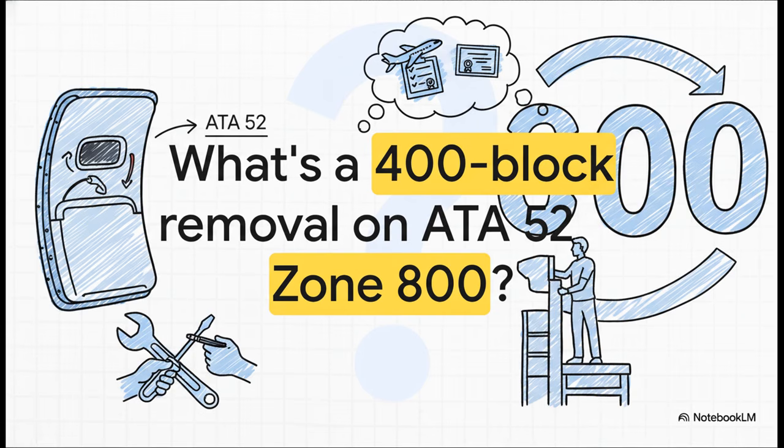Chapter 52, that means doors. Zone 800, that means you are physically located at the doors. And a 400-block procedure, that means removal and installation. So you are out there removing and installing a door component.